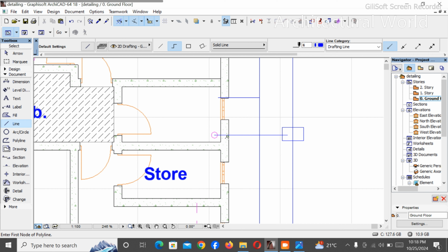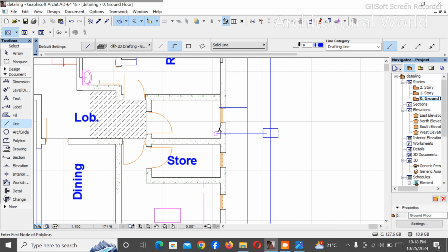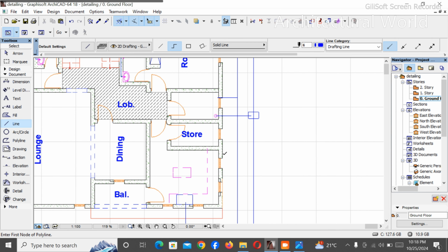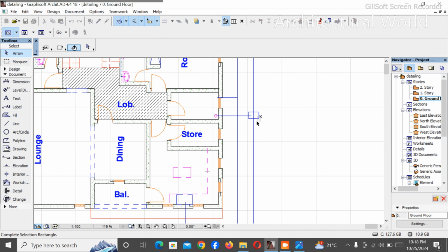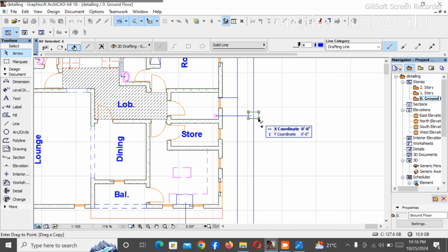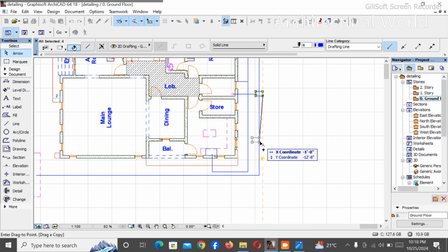This is a 2-inch waste pipe, and the washing machine waste will be connected to this 2-inch pipe for easy discharge. Then the next place you need a chamber is right here. You need a chamber here, you need a chamber here, you need a chamber at the edge, and you need another chamber right here.